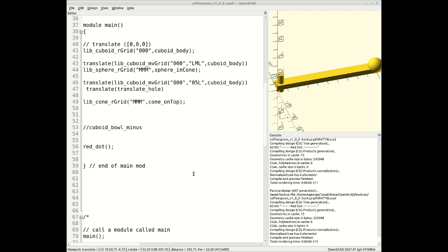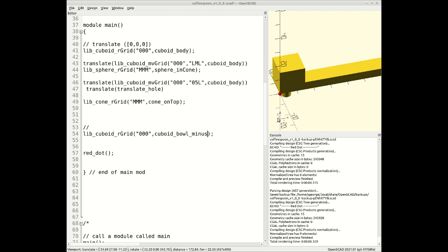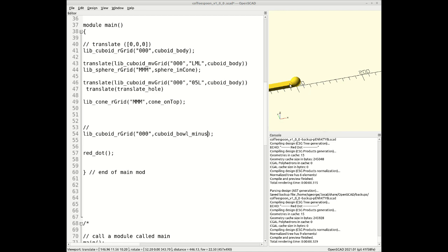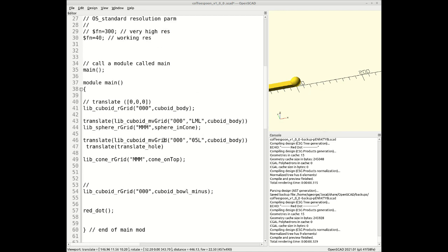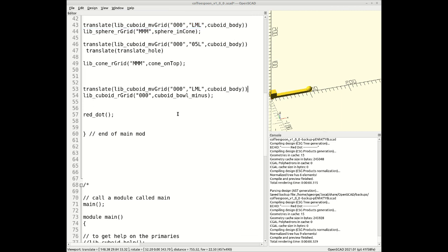So here's my object. Here's my render. And hit F5. Okay, so we're rendering it from this point here. Obviously that's not ideal. I want to render it all the way over here. Now, awesomely, I already have that translate ready to go. So you can see this translate here moves from here all the way to the middle of that sphere. All I need to do is copy it, pop it there.